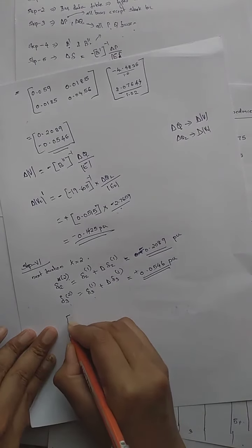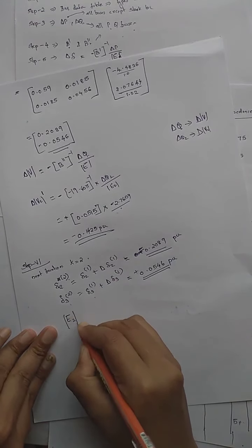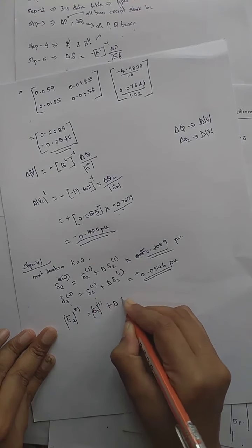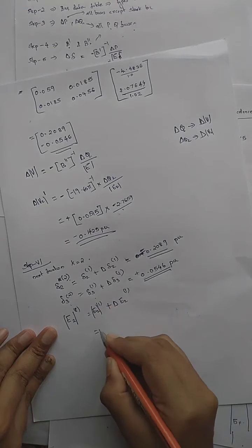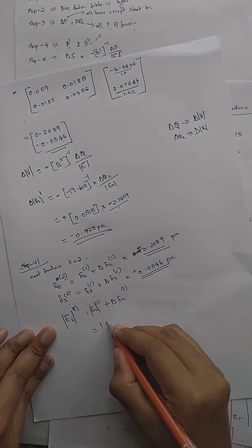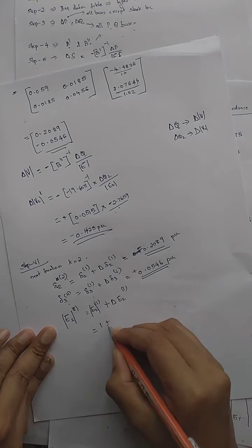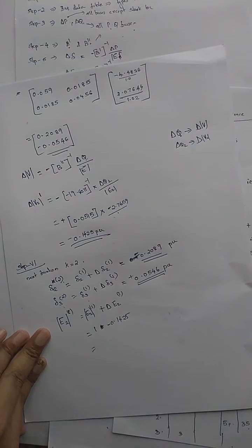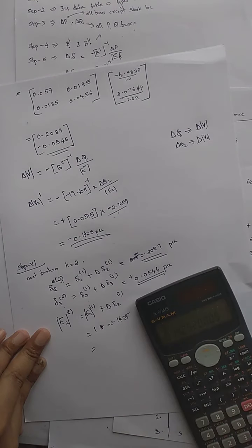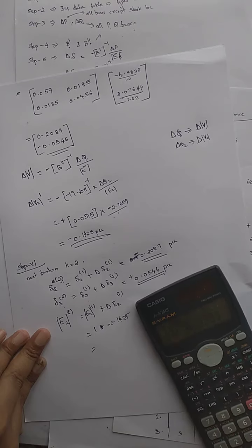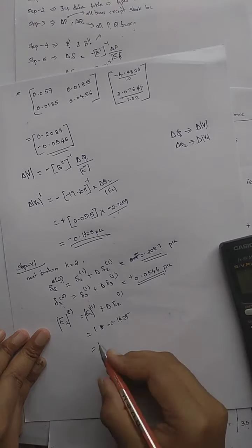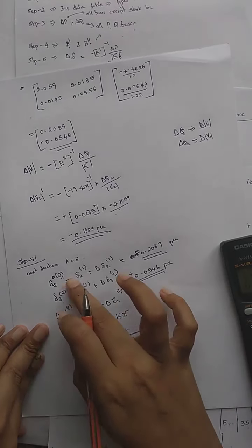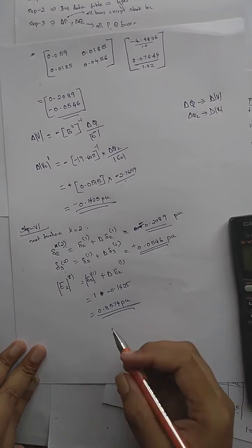And next we have to find out the value of E2. What is E2? E2 for my second iteration is equal to E2 for my first iteration plus delta E2 for my first iteration. That value E2 for the first iteration, I assumed it as 1, plus what is delta E2? So it will be minus 0.1425 per unit. So that is equal to 0.8574, isn't it? So E2 value is 0.8574 per unit.